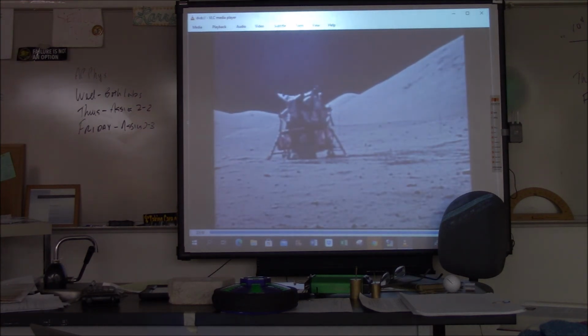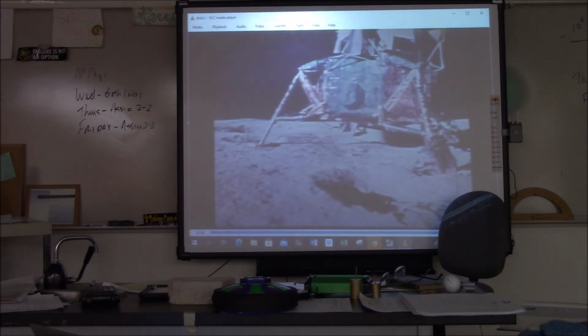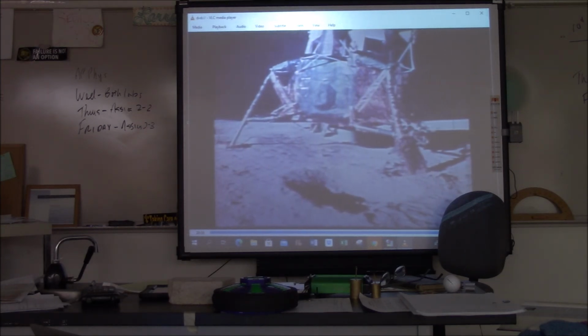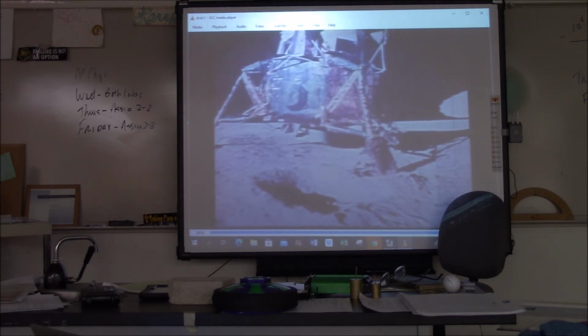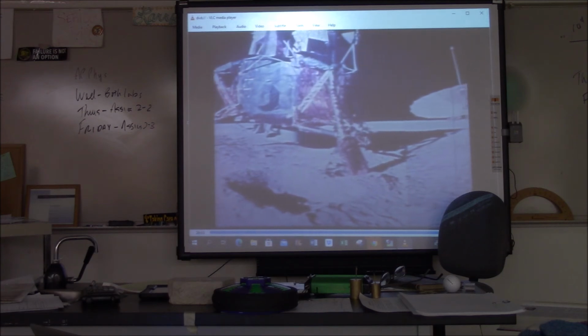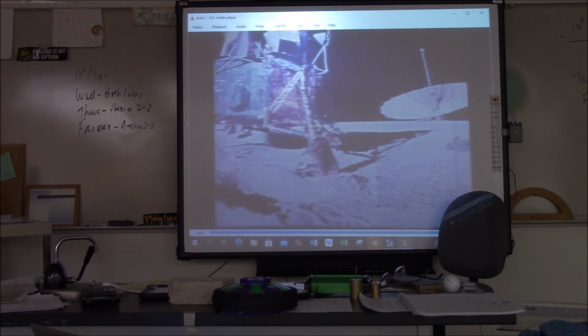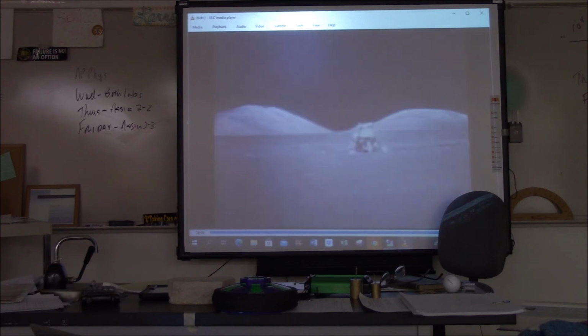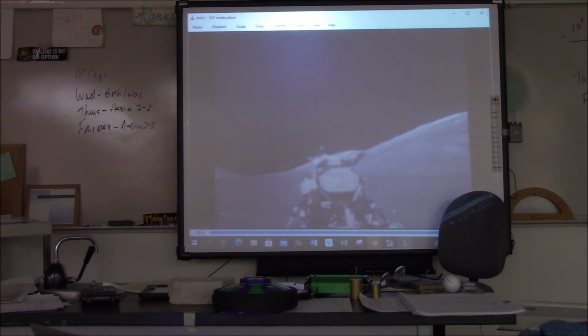In order to provide the thrust required to lift off from the surface and attain lunar orbit, the ascent stage of the lunar module possessed a single rocket engine. Because there was no backup engine and no other means to lift off from the Moon's surface, a malfunction could absolutely not be tolerated. The single engine had to work. The engine used the most reliable propellants available, hydrazine and nitrogen tetroxide, two compounds which spontaneously ignite upon contact with each other.